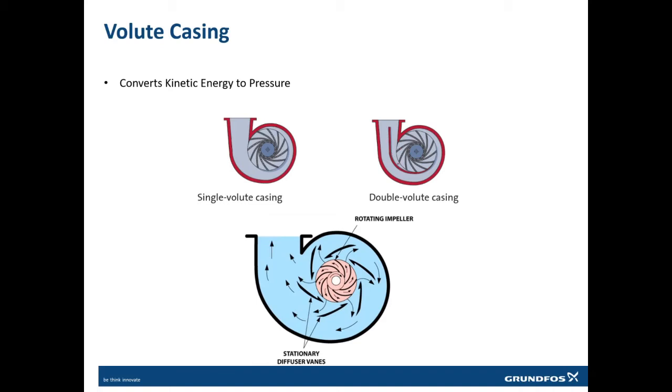What does this do? It reduces, or channelizes, the radial forces on the impeller, because once the water is pushed, the impeller is pushing against this wall. So by adding this additional vane, or additional wall, or partition in between, we divide the flow going out.